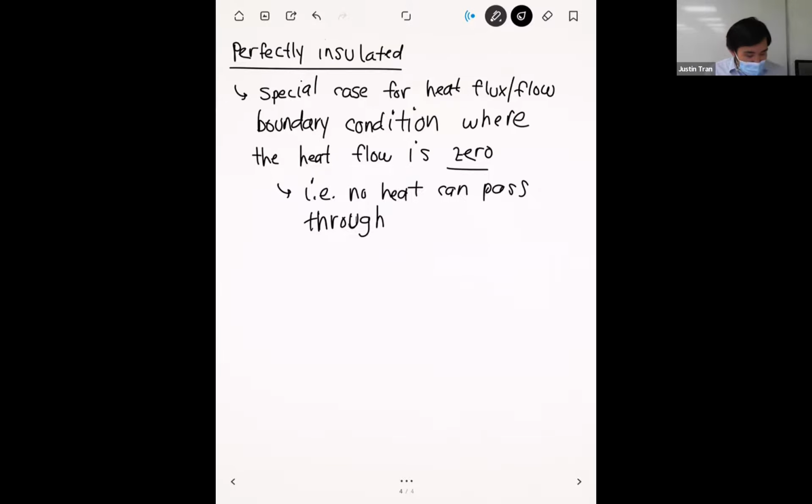And so those are the main constraint and load type boundary conditions. Let's talk about some more specialized thermal boundary conditions that don't have an exact analog to structures, but they're very important for heat transfer. So now let's talk about a convection type boundary condition. Just like I mentioned before, convection is the heat transfer usually from one solid object to a moving fluid.